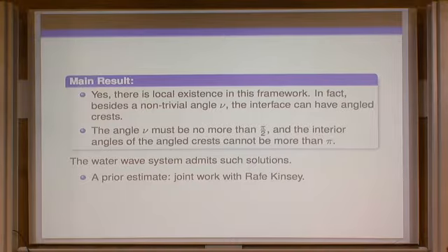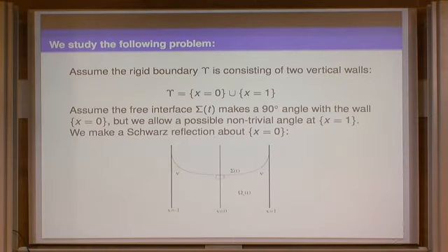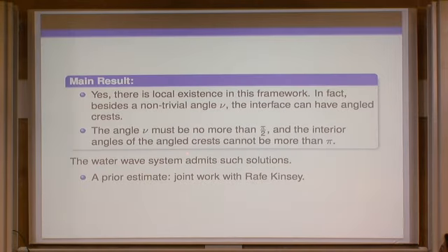Okay, so anyway, what we find is the angle mu, this is the angle with the wall, has to be less than... let me be precise. From the equation, we learned that this water wave equation with no wind, no surface tension, no vorticity tells us that you cannot have this angle be greater than 90 degrees. So if this is your wall, your water never comes in like that. That makes sense, right?